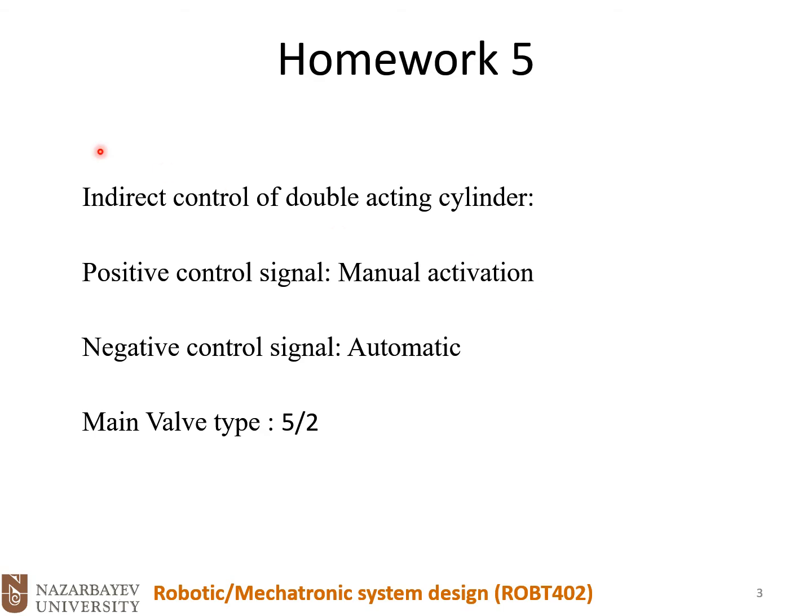So having indirect control of a double acting cylinder, the positive control signal is the same as the previous one, manual actuation, and the negative control signal is automatic. So this is something new here for you. The main valve type is 5x2.